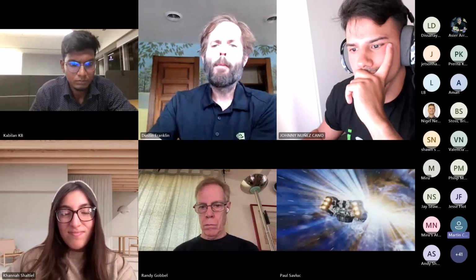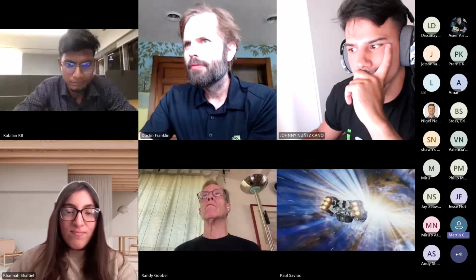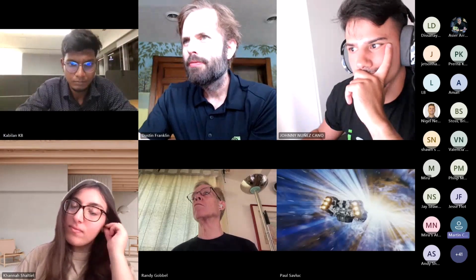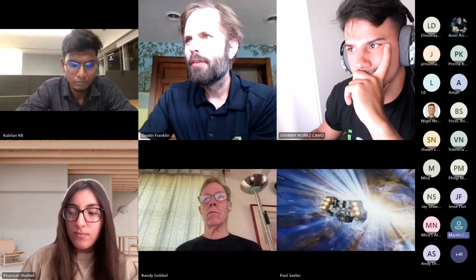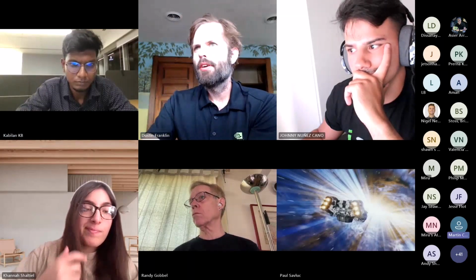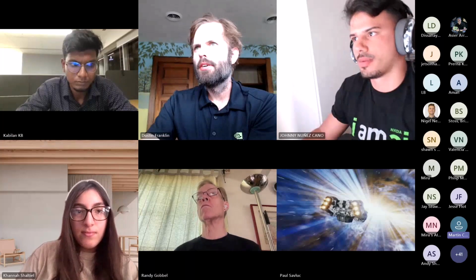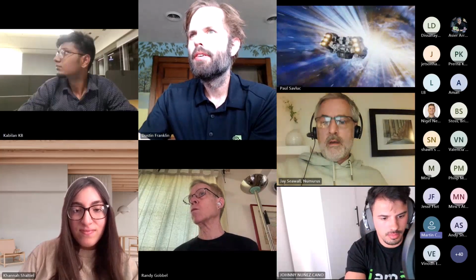Yeah, so I have a contribution where I tested all these different ROS middlewares. I can put a link in the chat. Basically, there's Cyclone, FastDDS, Zenoh, and also when you have images, point clouds, and so on, you want to use zero copy. So there's a combinatorial explosion of all these different settings. So I made a repo. I can share it with you. It's mainly aimed towards depth cameras and so on, and I tested it on Jetson. Awesome. Okay. Yeah, drop a link in there, and I'll dig into it.